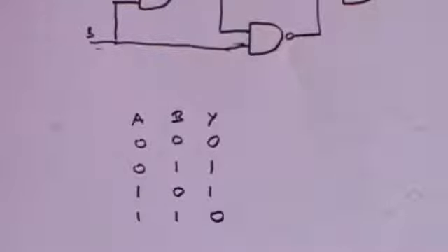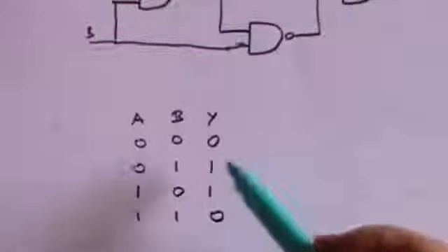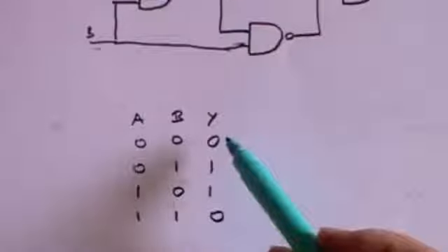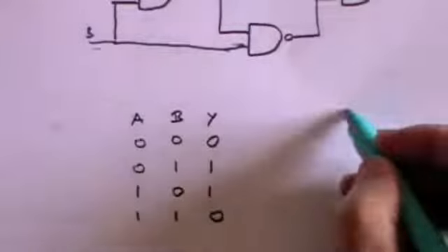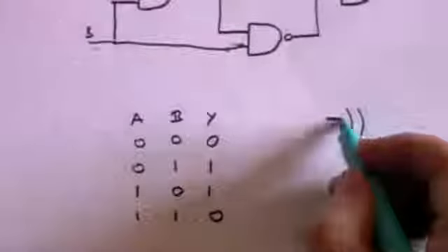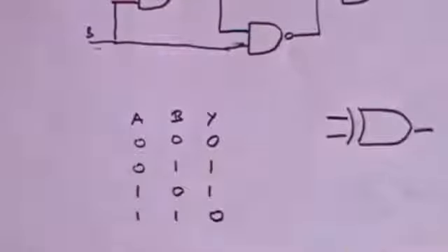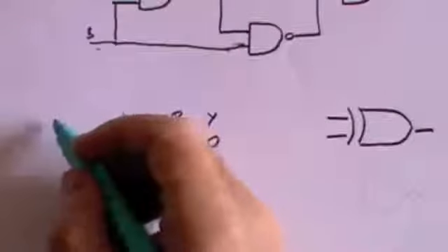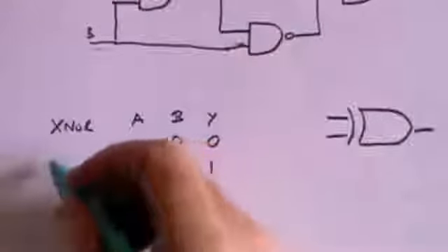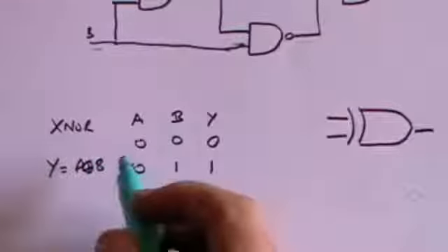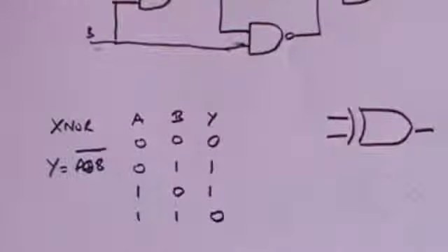And that is your XOR gate. You get a positive out if one or the other is positive, but not both and not neither. And the diagram which reflects the XOR gate is this one. And that just leaves us with one more to do, which is the XNOR gate, which is Y equals A plus B with plus in a little circle, but we put a line over it to show that it's a NOT.